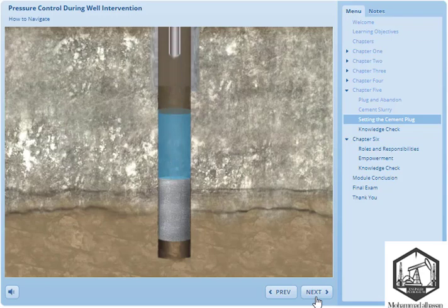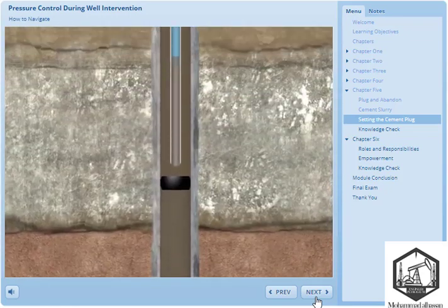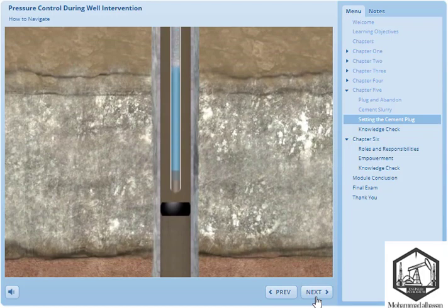4. The drill pipe is then pulled out slowly, leaving the cement plug in the correct place and at the correct height. In the cased hole section, a packer may be set to support the weight of the cement until it sets and further reinforce the barrier. These procedures will be carried out for all cement plugs.